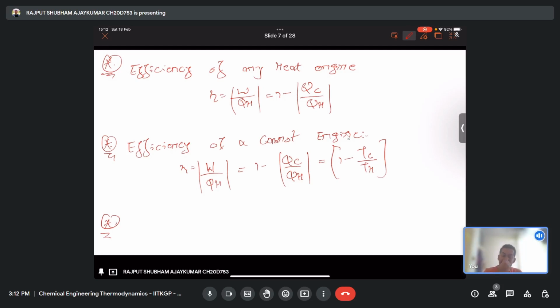So if you take any adiabatic irreversible process, how can you identify whether the process is isentropic or not? We have shown already in week 2 that the change in entropy is determined by integration of dq by T. Now you can integrate the system, and for an adiabatic process there is no heat flow in and out of the system, so Q will be 0. So you can say the delta S of the universe continuously goes on increasing. So for the adiabatic process, delta S is greater than or equal to 0. This is what we have already covered.